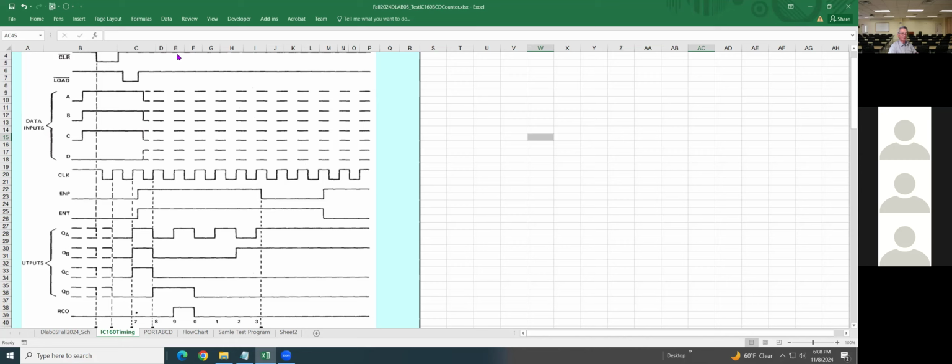That's the requirement. Now if you apply the clock next, they go to number 9, 1, 0, 0, 1. If you apply the clock again, what number? 0. Perfect. That means they count from 0 to 9, and 0 to 9 goes forever if you keep applying the clock.